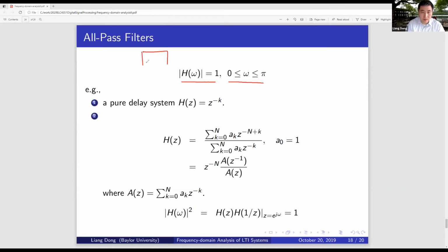So for example, I have a digital resonator here, which is a nonlinear phase filter, and that's the input signal. Then I cascade an all-pass filter. The all-pass filter is not going to change anything about your resonant frequency, but it can change the phase. By a well-designed all-pass filter, you can have a y(n) where the entire signal looks like a linear phase. So y(n) is simply a delayed copy of x(n), but with a very good amplitude emphasized on the frequency.